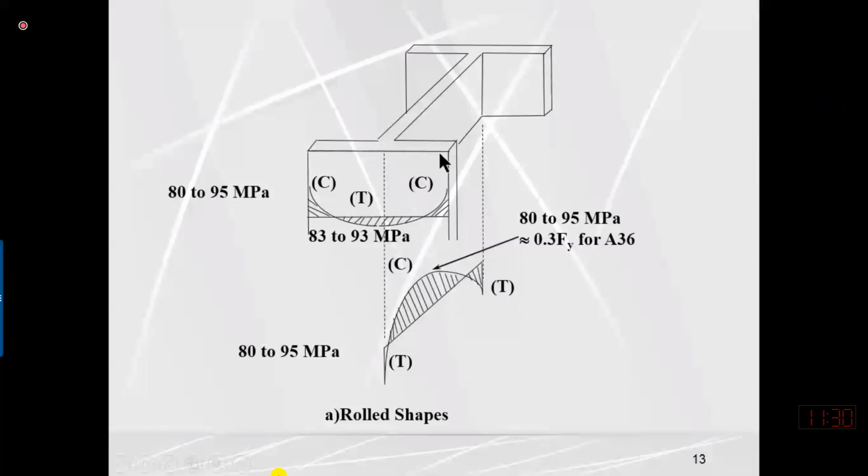And when the material shrinks, a negative strain is produced, the tip length is shortening, so elastic or compressive strain is produced. Strain multiplied by the modulus of elasticity means that due to shrinkage the flanges are subjected to compressive stress, and the junction, because it cools down slowly or gradually, is subjected to tensile stresses due to the shrinkage of the flange.